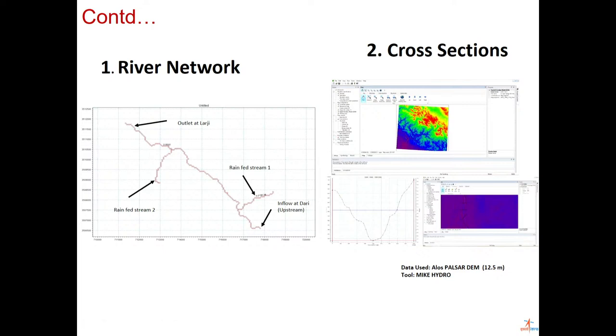Sometimes you will have base layers in the GIS software. That image, those base layers, you can also use, and using that high resolution image, you can delineate this particular river. Once you delineate, you can save this river network as a shapefile, and then import the shapefile into any software. The interface you are seeing is of the MIKE 11 software, but you can follow the same approach in open source software like HEC-RAS also, where you can set up a hydrodynamic model and define the river network with the help of GIS software. This is the first approach, where you take help of a satellite image.